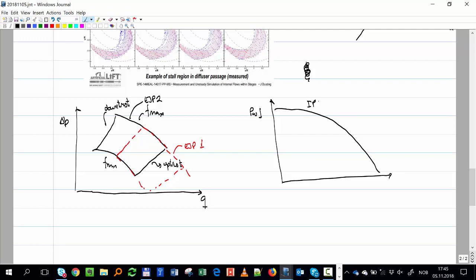Well, it should be a straight line, right? We are talking about oil. IPR and TPR, and we know we want this Q with this delta P. Now let's say that combination falls here. Which pump should you use? Pump 1 or pump 2? Pump 1. Why?